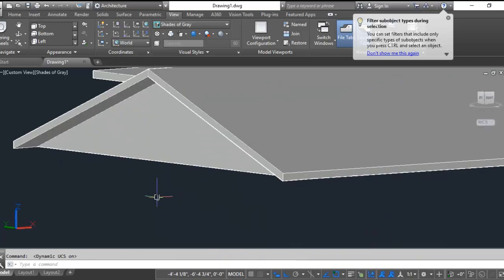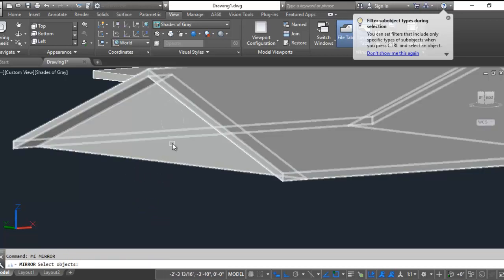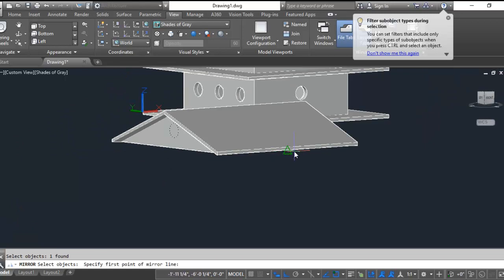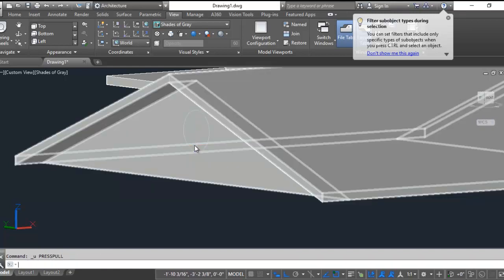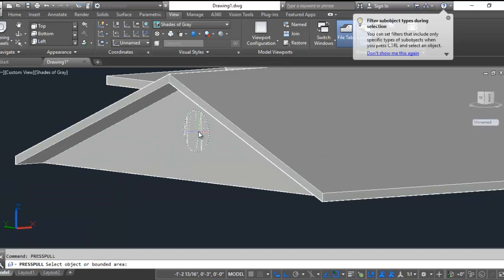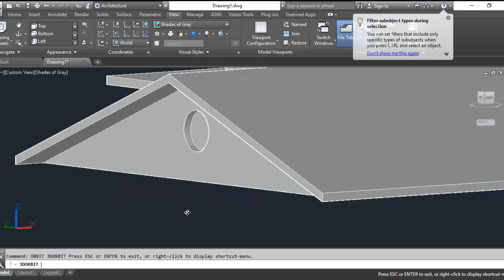Now the last feature they want is a circle that's depressed. So I'm going to turn back on that dynamic UCS and do a circle on this face. So hover over the face and then come down to midpoint, diameter 2.5 again. Move it up, maybe 3. Now I'm going to go ahead and mirror it to the other side so I don't have to do this twice. So from the midpoint, even though I can't see it, it should be back there. Now if I press pull that circle, and I go, oops, I just went an unknown distance. Press pull, circle. If I hover toward the inside and type in 0.5, I just have a 1/2 inch depression, which is what I'm after here for the look.